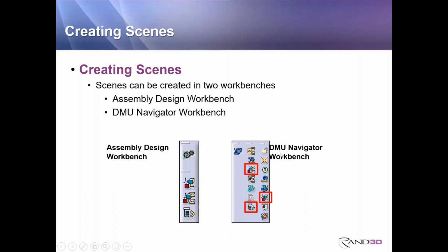And then if you're using the DMU navigator workbench, the digital mockup navigator, which has some functions for being able to view assemblies, you will also have the ability to create scenes. Now, they will be found on different toolbars, but the same functions exist in the DMU workbench as they do in the assembly workbench. Now, to build your scenes, we're going to use enhanced scene, which is right here or right here.